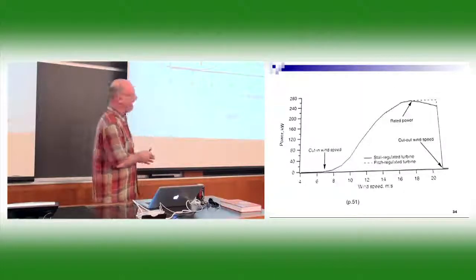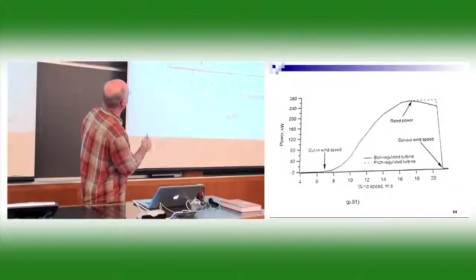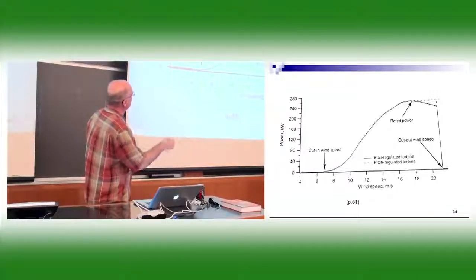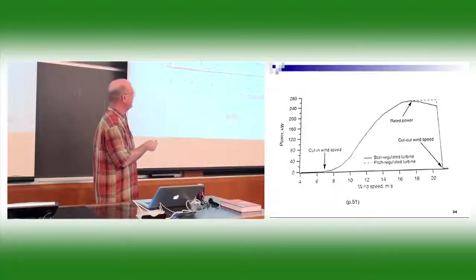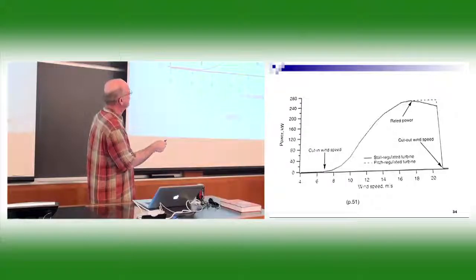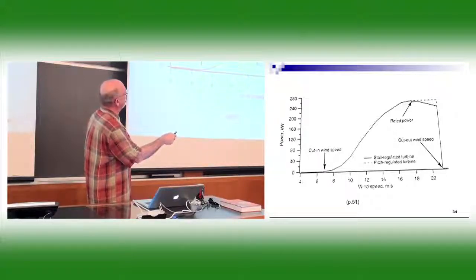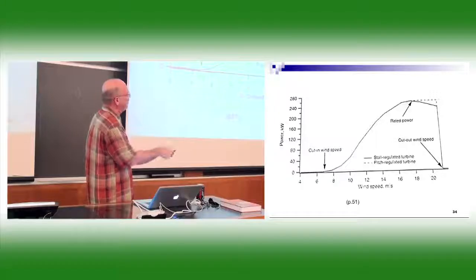If you look at a curve here of power versus wind speed, normally it goes to the cube. But you don't get anything until you cut in. So you cut in here and finally you get some. But then as you go up, your losses get more and more. Finally, this is all the power you can take. You can't take any more, and as the wind goes faster, you've got to start throttling back and finally shut down.